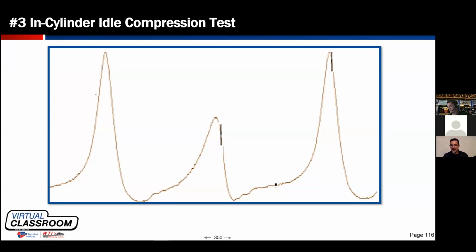Could I have advanced camshaft timing, meaning the exhaust valve closed early? That could certainly happen. Again, how many cylinders would that affect? It depends. If this was a push rod engine with one cam, it would affect both banks. If it's a camshaft on only one bank, like an overhead camshaft, it would affect all 4 cylinders. So again, we're down to 1 cylinder.